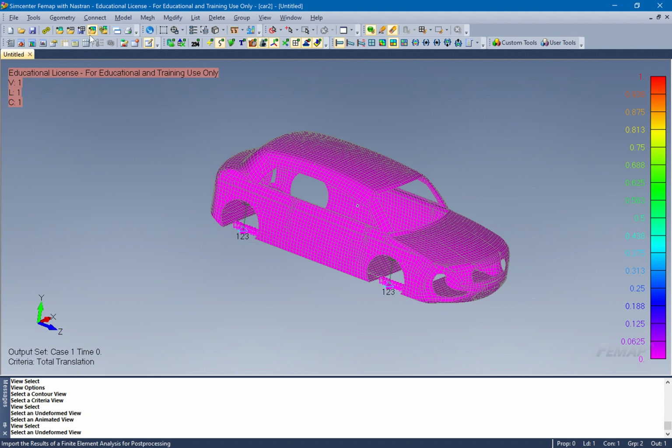Could you give me the transient damping ratios and stuff like that again with the steps? It was 0.05, 0.05, 20, and then what was the number of steps? 2000? Yeah, 2000, 0.001, output 5. Okay, so I think we should be good.